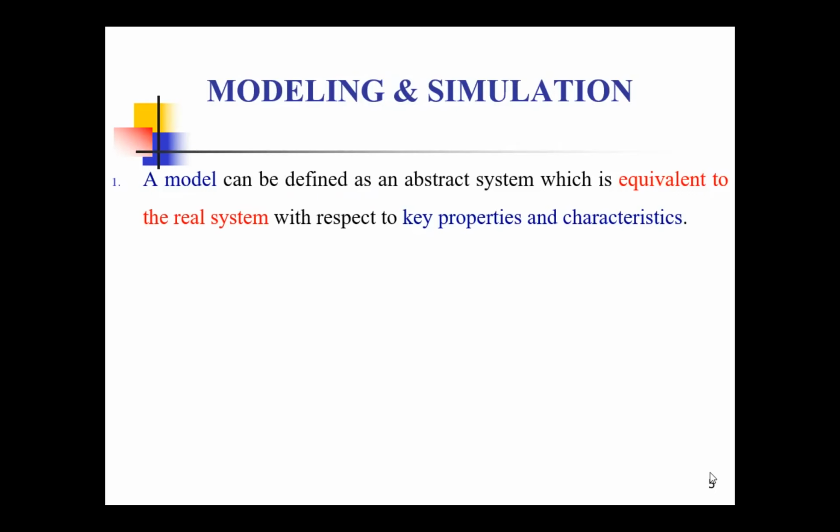The characteristics are, we have a material for the workpiece. We have a material for the tool. We know how it is going to be interconnected. What are the properties that both will have? The tool should be rigid. It has some geometrical factors, for example, a relief angle, a nose radius.